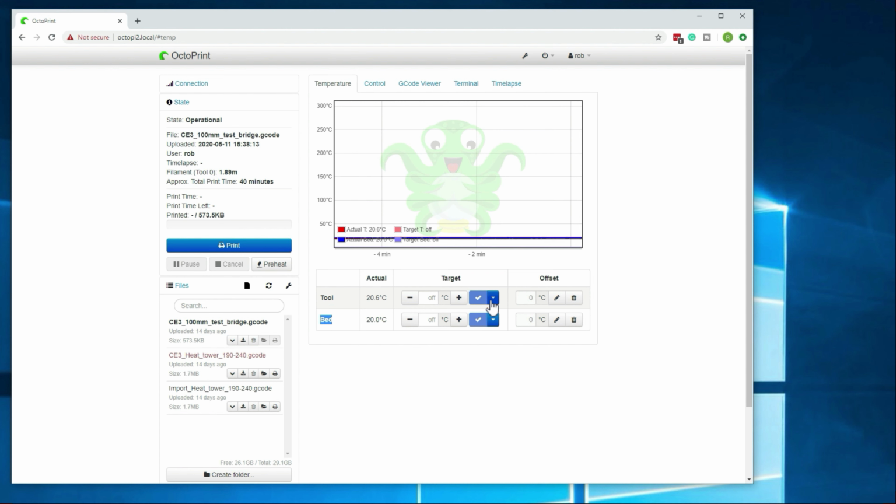So for example, if you go here and go down to set PLA, it's going to start heating for PLA. So now you can see that it set the target temperature at 180. Every time I scroll over to show you, it goes to off because that's where it's at that point in time. But it shows 180 Celsius, and then the actual right now is 34.8. All right, but let's go ahead and turn that back off. So if you wanted to turn everything off, you just go to off here, and then same down here.